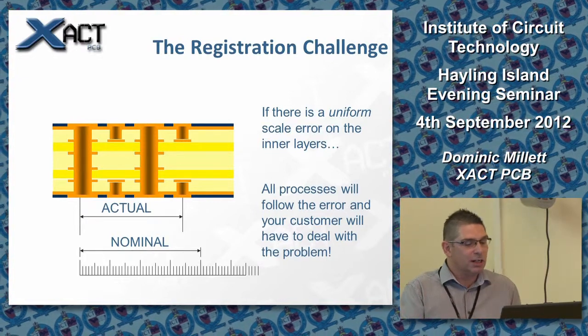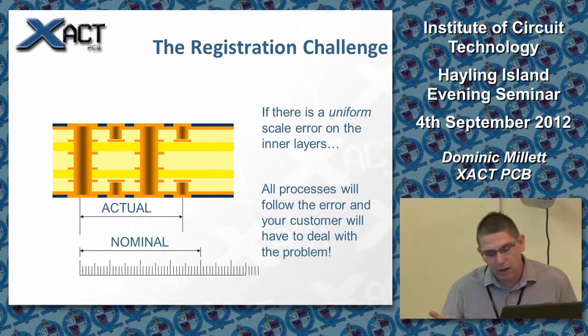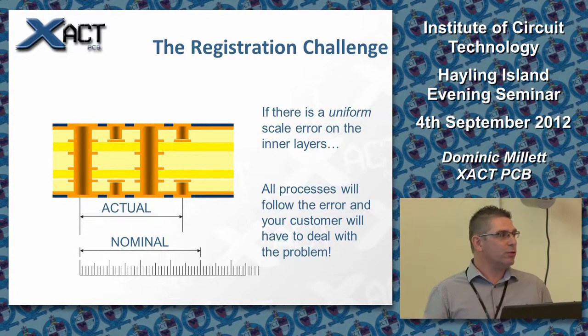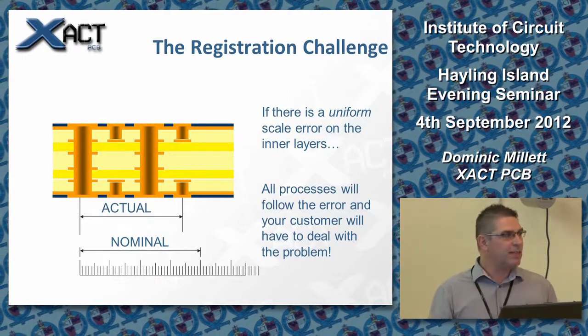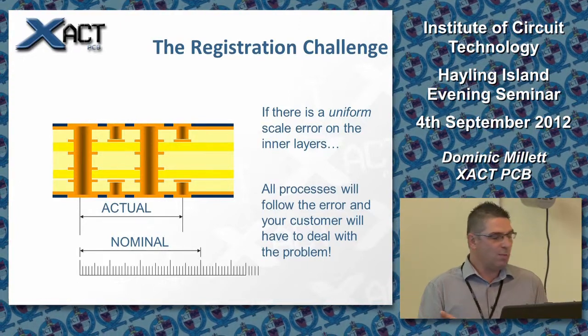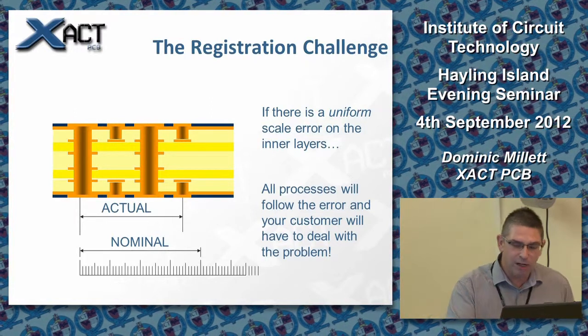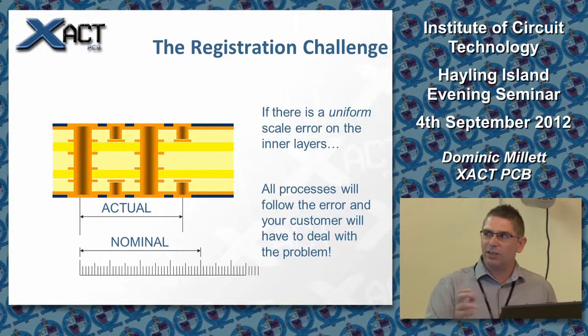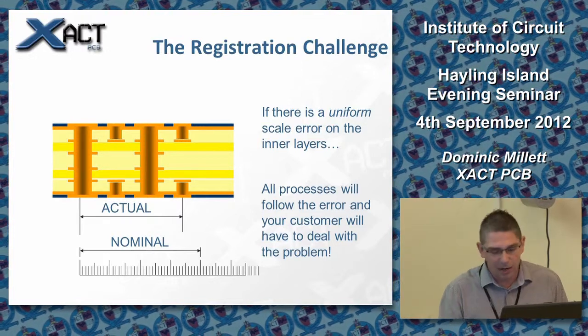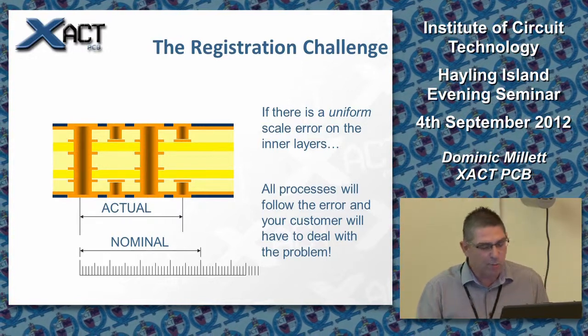And I've heard of this time and time again where stencil screens just don't fit the boards. I've heard of cases where a particular board needed 3 stencil screens just to get the board assembled. All because the board manufacturer did a little bit of scaling, a little bit of fixing, and thought they delivered a product on time, and all it did was cause the assembler a real headache.